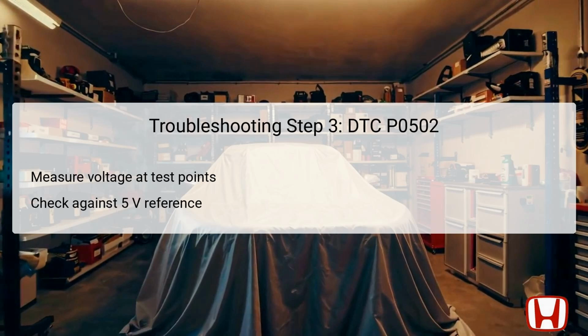If about 5 volts is observed, the next step would be to check continuity and integrity in related circuits. Conversely, if the voltage is not present, the technician must consider potential open circuits, indicating issues that need to be repaired before proceeding further.